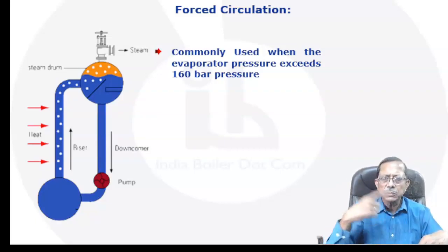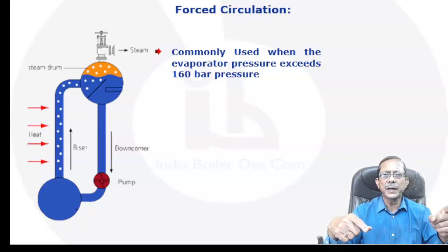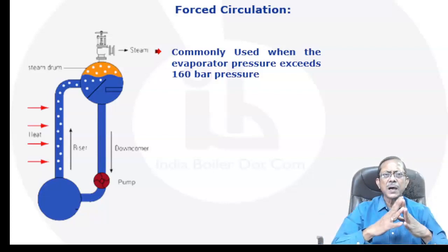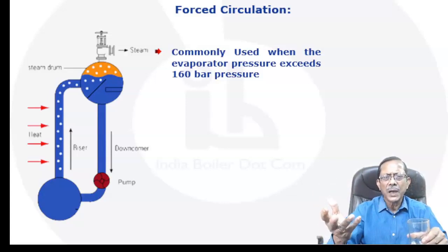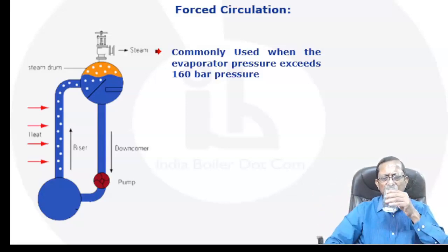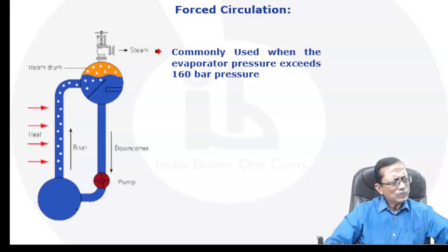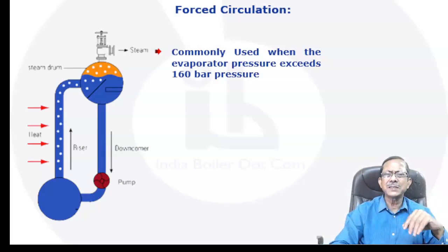We first start the circulation pump and then we start the reactor, right? So this sort of thing can be seen in industry, and you may wonder what is the purpose of the circulation. I hope this particular discussion is going to give you all these answers. Now in a forced circulation system, there are certain advantages. Since the circulation is taken care of by a pump, the head loss due to friction and all that, due to which the natural circulation is mostly affected, is not a problem here, right?